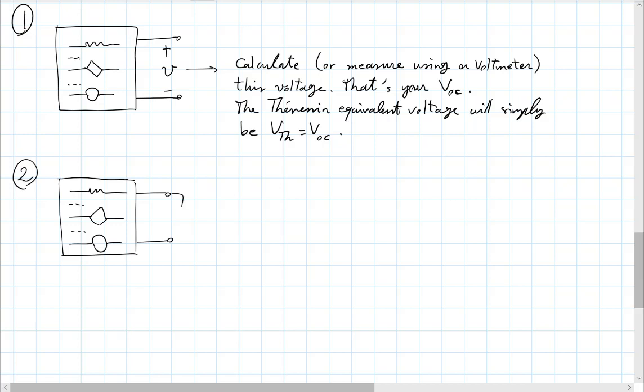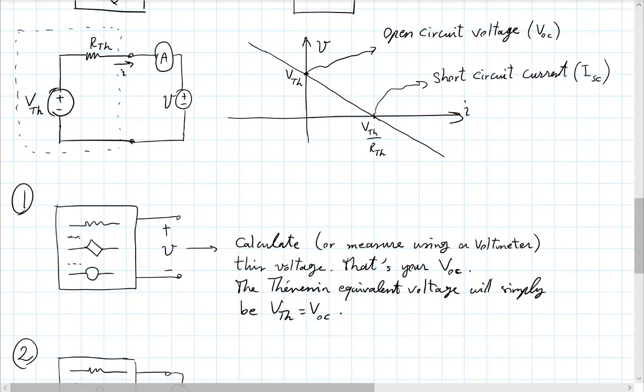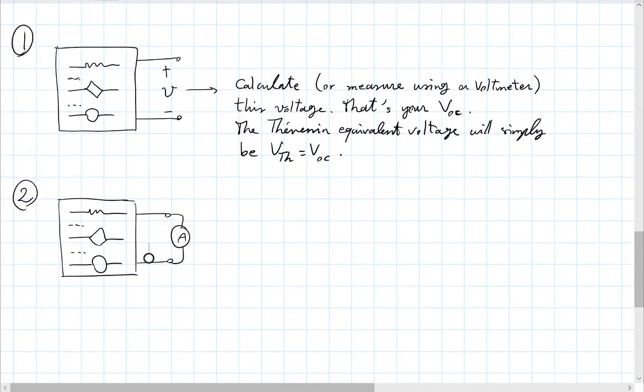I connect an ammeter. And an ammeter, again, has 0 volt drop across it. So it really is like a wire, an ideal ammeter. It's just the wire that has a number on it that you can read. And that's the current going through it. Now, notice the way I have defined the convention for the current there. If I want a graph like that, the current going from left to right. So this is the current that I'm interested in.